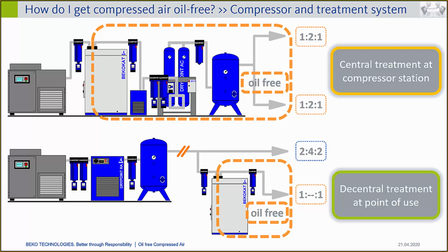Okay, and one last one just dropped in. Will the use of a pre-filter extend the catalyst lifetime? I wouldn't say it will extend the catalyst lifetime, but probably it will guarantee for a longer time that the pressure drop inside the catalyst tower will not increase, because it's easy to exchange the inlet filter regularly, but you cannot change the catalyst every year.